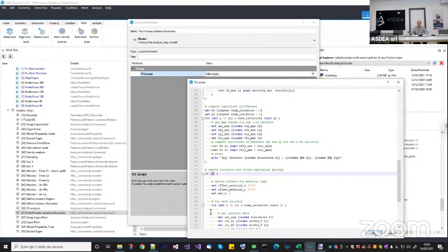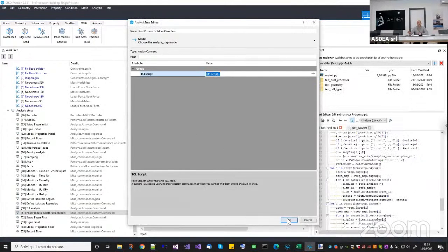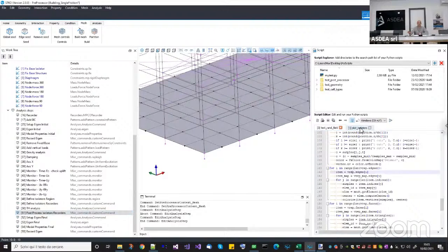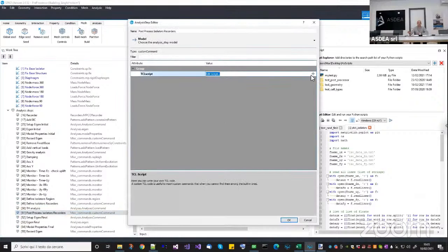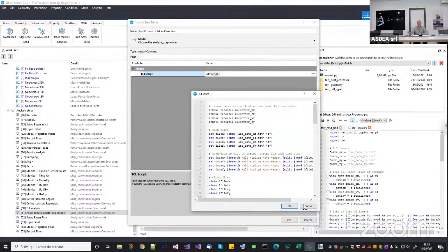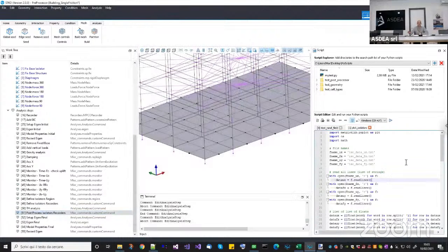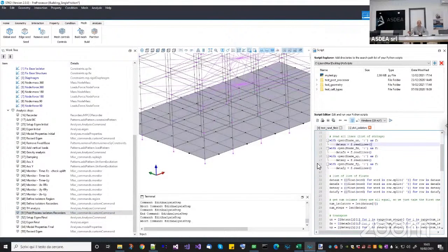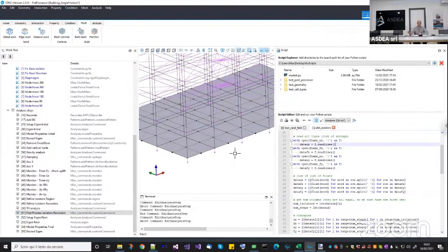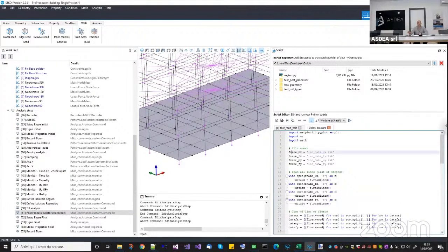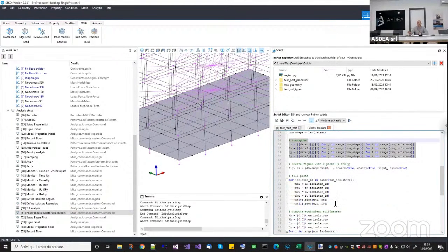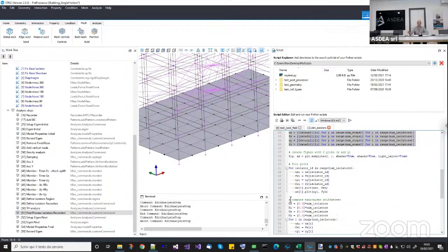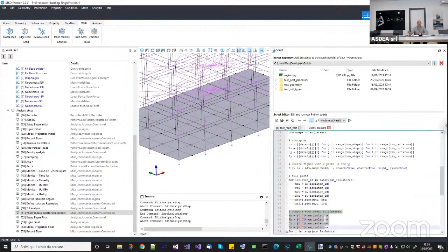That before was switched off, now I switch it on, so you can see the difference, okay? Now, before explaining how it works, I want to show you something in the postprocessor, because I understand that it is quite difficult to understand how it works just by looking at the code. So I took advantage of the Python scripting in STKO to show you exactly what that script is doing, okay? That script is basically taking these four files, reading them, computing the X and Y maximum displacements, and then computing the equivalent stiffness. So let's see how it works.